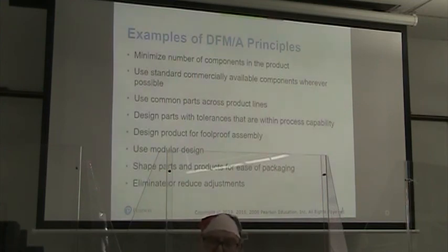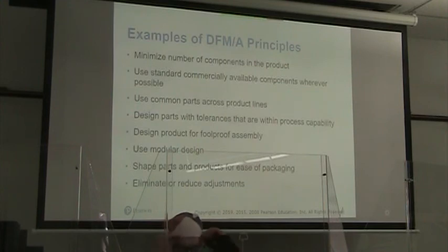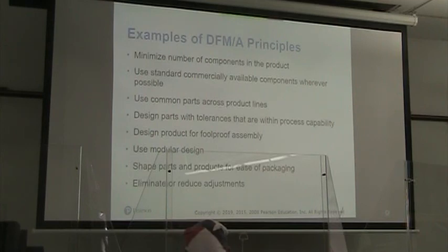Design the product for foolproof assembly. What can go wrong will go wrong, as the old adage reminds us. Use modular design. In other words, if we're able to take part of the assembly apart while other parts of it stay together, that's going to make it easier.